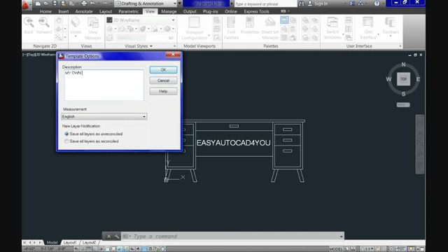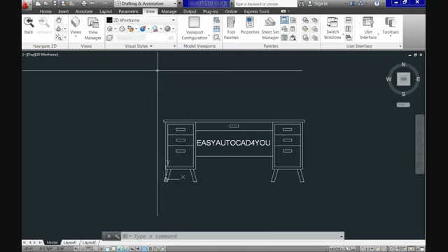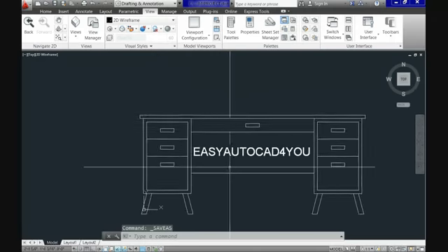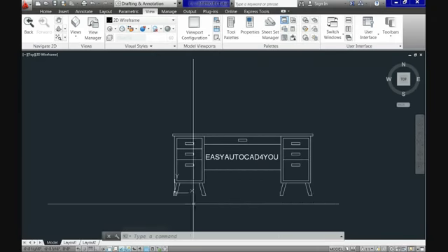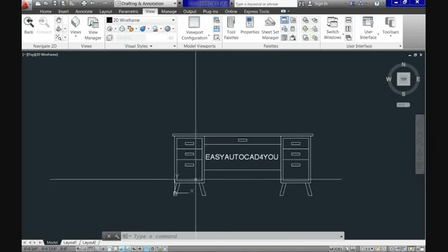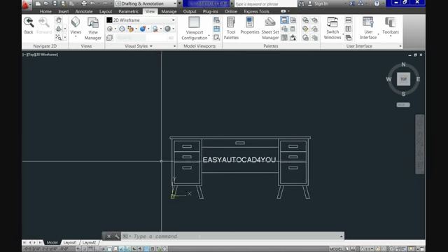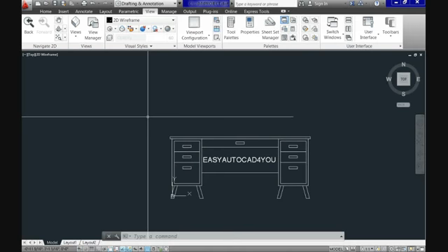In this case, let's put there my own DWT to test. And that means that every time you open up that DWT or template, all the settings you saved there are preset or pre-saved by default, and you have it ready just to start drawing in your new drawing.